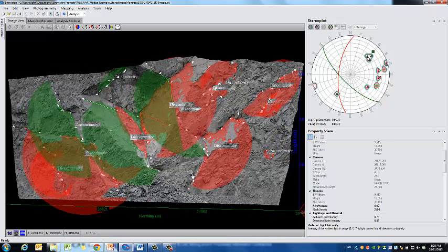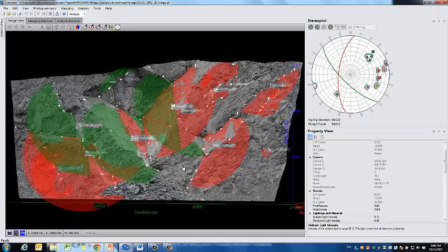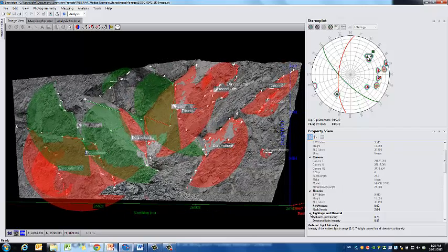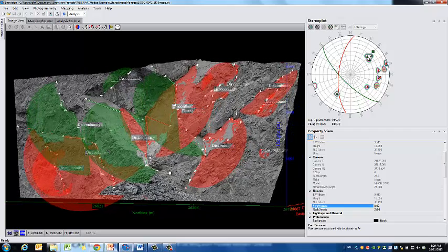In the 3D image, what we've added in 5.1 is domain characteristics for this 3D image. So what we can do is go into the property view for this image and add geotechnical parameters such as pore pressure and rock density in this case. Now at the moment in the software we can add those domain geotechnical values to the whole 3D image.